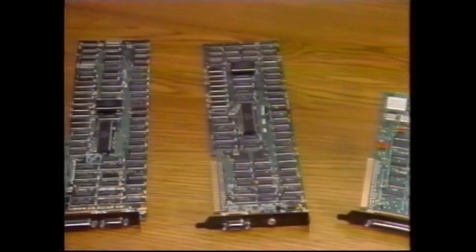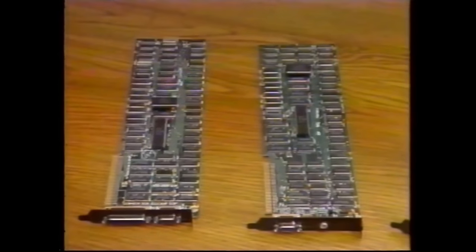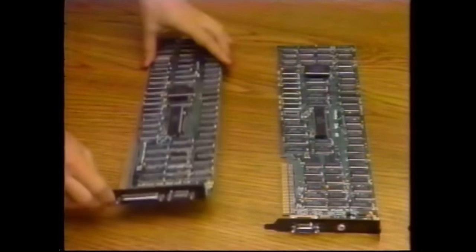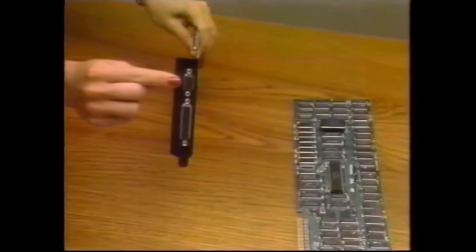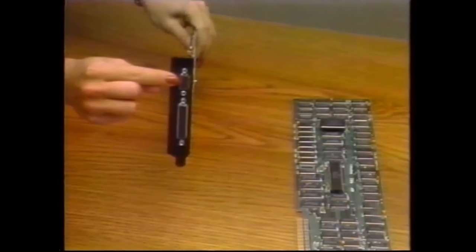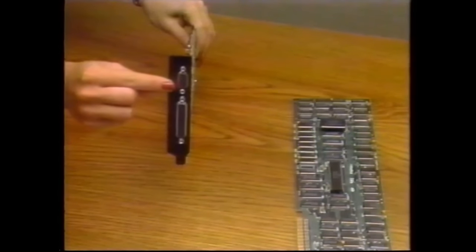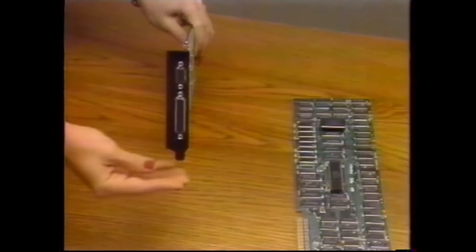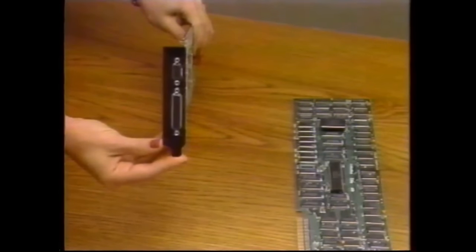However, you'll most certainly have one of 2 IBM video display cards. There is the IBM monochrome display parallel printer adapter. It is really 2 different circuits on one board. One of these circuits is where you would connect the IBM monochrome display, if you're using one. The other circuit is where you would connect an external device requiring a parallel output, such as parallel printers.